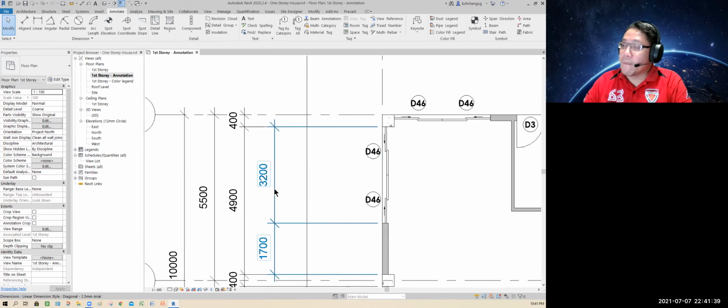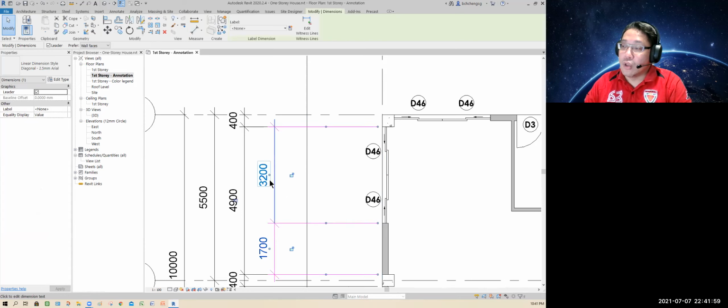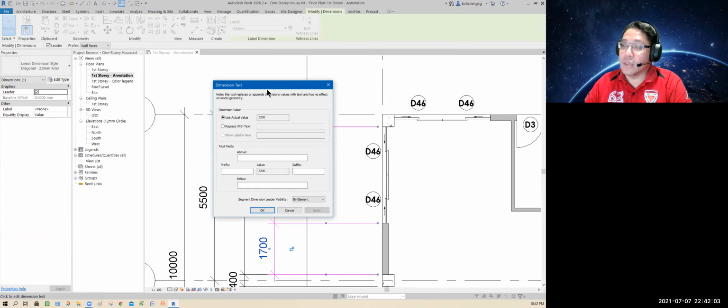But meantime, if you really need to put or label there, maybe in Archi, you might not say structural opening. It says what? 4-panel sliding door. But you can't type directly from there, right? So how? Look carefully, select your text once, not the grid, pick your text one more time.